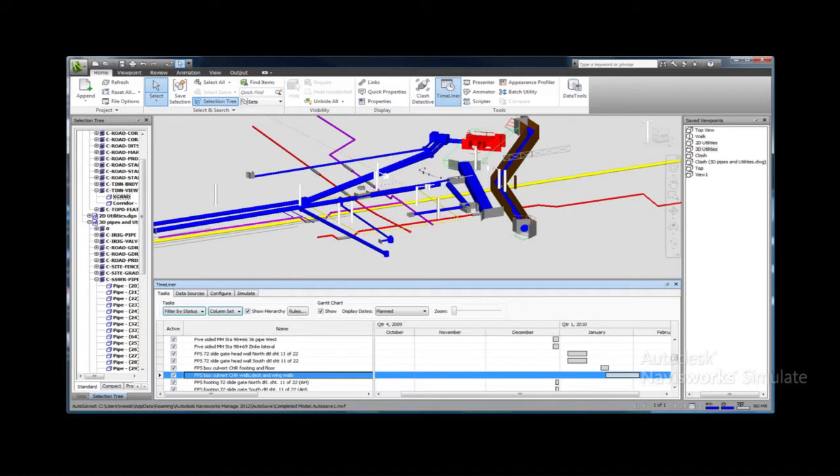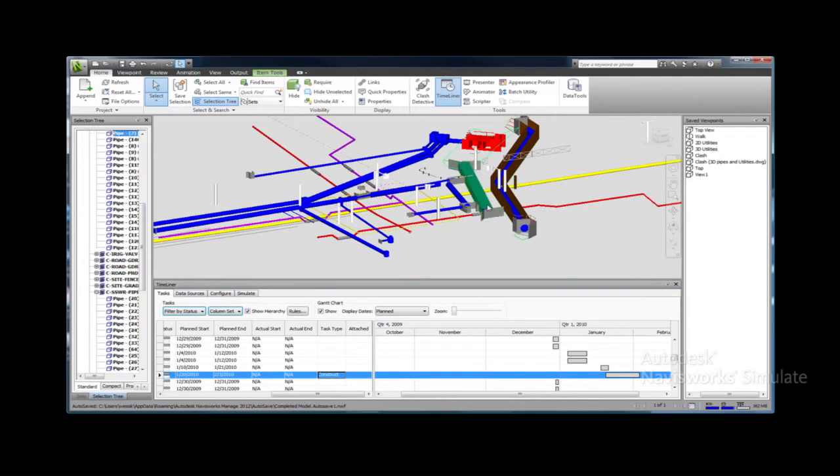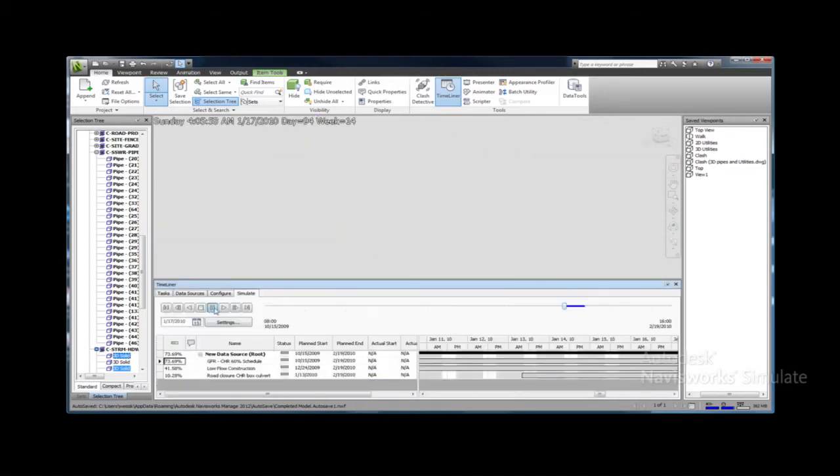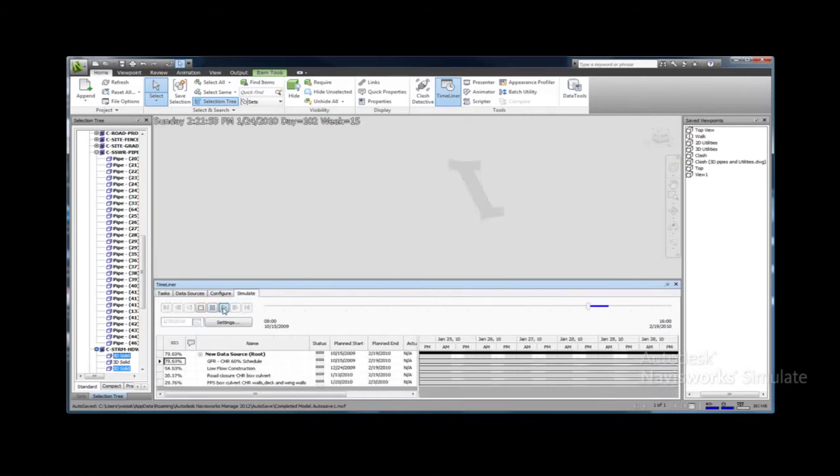To do this, an individual task is selected from the task list. Here, you can select a specific box culvert wall, deck, and wing walls. Once the task has been selected, the task type is defined. You are interested in the construction of the box culvert, so the construct task is set. Objects from within the model that will be associated with this task are picked. With the selection complete, attaching the current selection is then executed. Then you can examine the simulated construction of just this box culvert.